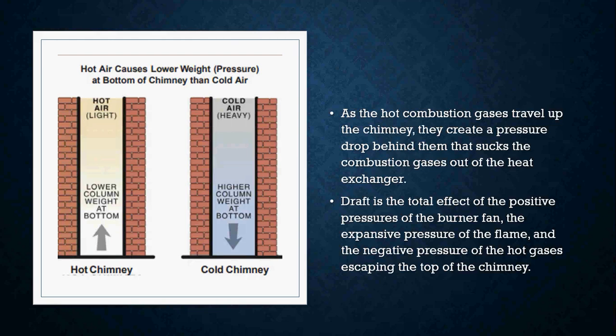Okay, so the draft really is a combination. It's a total effect of a couple of different areas. One, it's the positive pressure from the burner fan. Okay, it's from the expansive pressure of the flame and the negative pressure of the hot gases escaping to the top of the chimney.